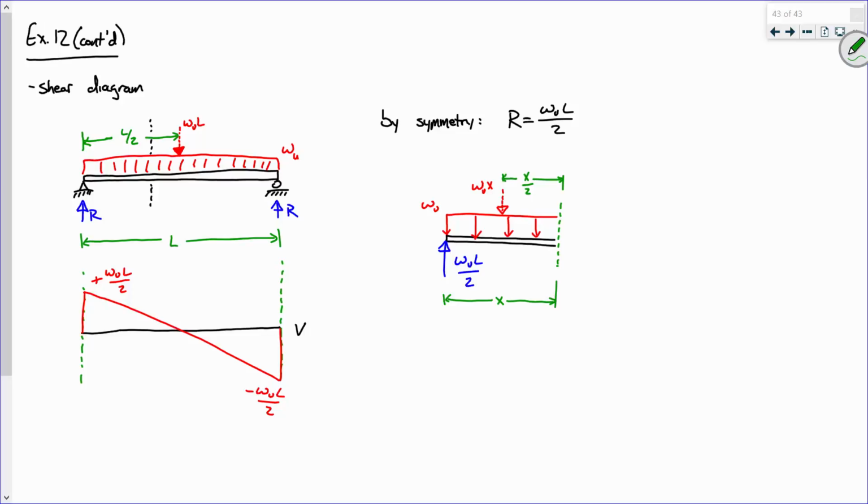And we need to determine the unknown shear. Remember, downward shears, right? So I'm going to call this V sub u, but it's V sub u of x. It's a function of x, right? Now there's a moment there too, and I could draw it if you want, but it doesn't really matter. Okay, there's your moment, but it doesn't really matter.